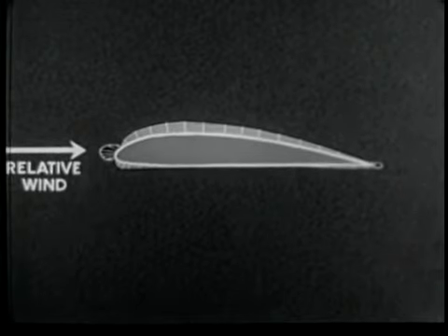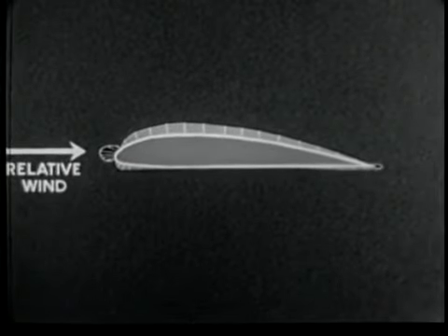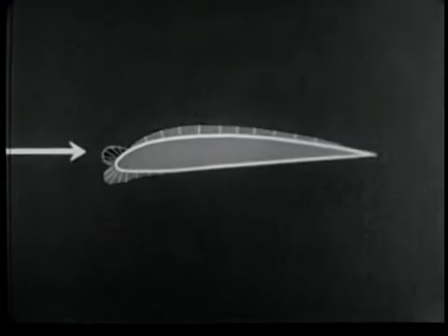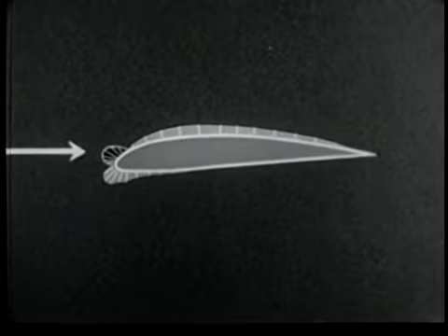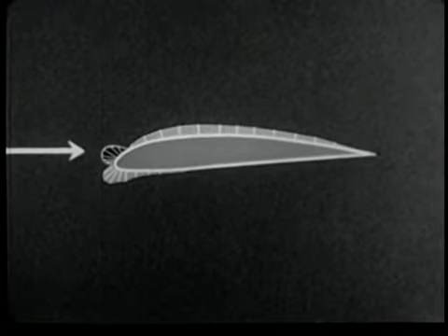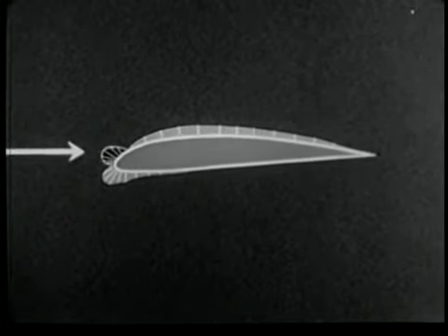Now let us see what happens to pressure values and distribution at negative angles of attack. From 0 degrees, the angle is decreased to a slight negative value. The positive pressure bulb on the leading edge is practically unchanged.